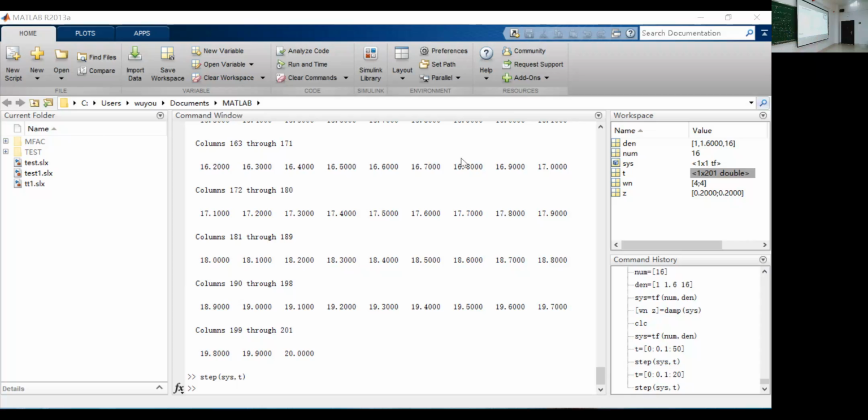And what about the others? Settling time. Remember, if you choose another point, it comes out and tells you the settling time is 4.9 seconds. And how about the rise time? Remember, what is rise time? From 10% to 90% of the final value. The rise time, right? And it's showing here the rise time is what?